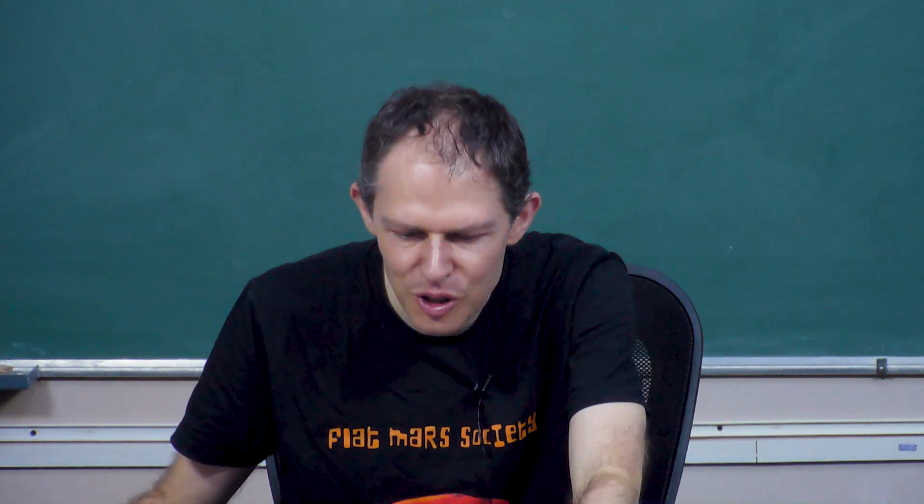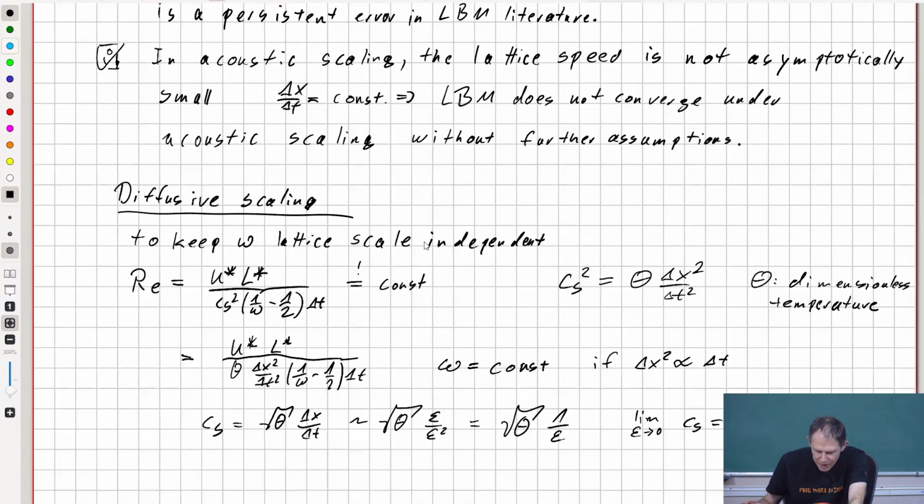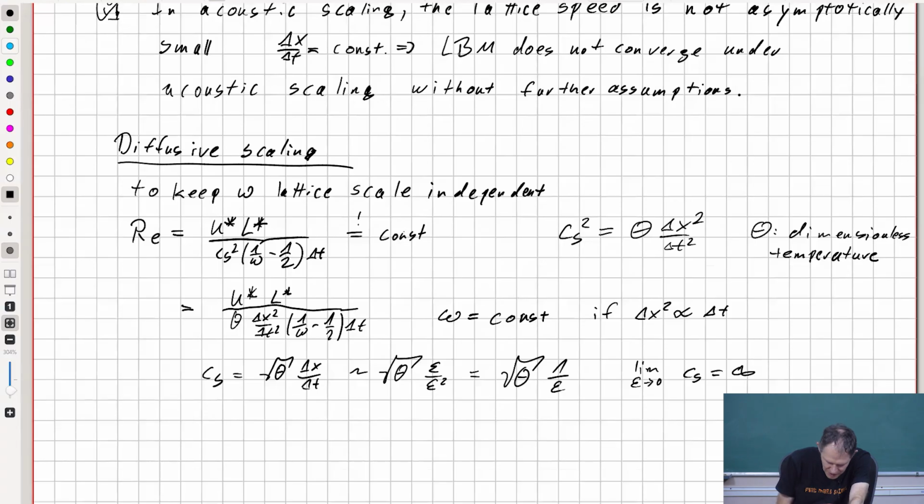So we get convergence. Yes, because the simulated velocity now gets asymptotically small. Now it's true if we have an error term that is u cube somewhere in our results, and we refine the grid, then this u cube error actually goes asymptotically to 0. It will vanish. For smaller and smaller grid spacing, this error becomes smaller and smaller compared to the solution.